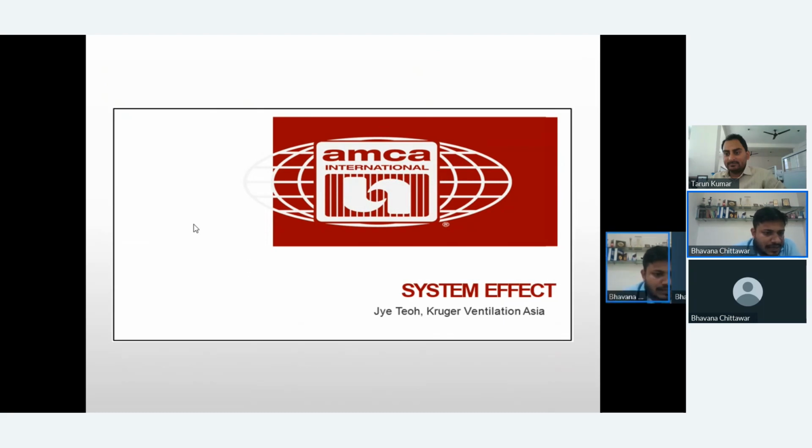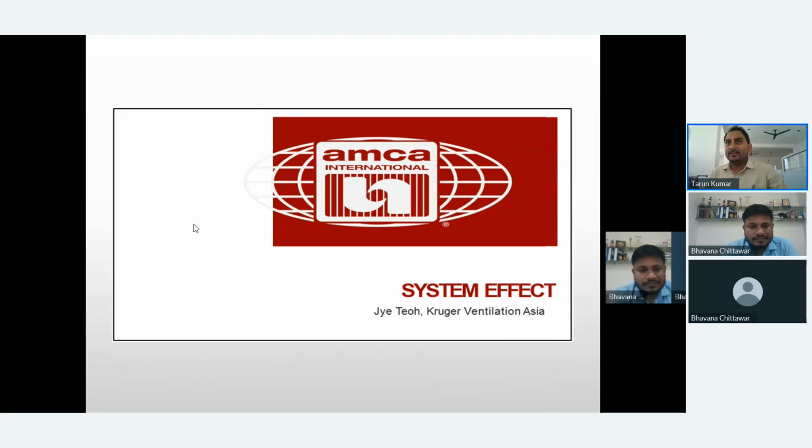Another question is, sir, what is the EC fan and EC plus fan? How do they consume less power as compared to DIDW fans with induction motor? See, the EC fan is a very good concept that came into the market for energy saving. Basically, the EC and EC plus fan use a complete BLDC motor, and it is not that it is always much more power saving than the DIDW fan. It depends upon your CFM and static pressure.